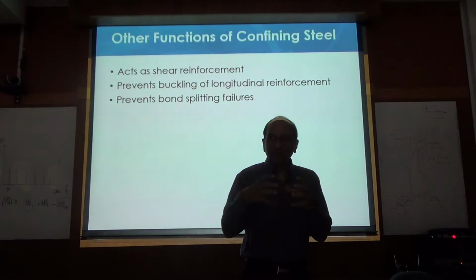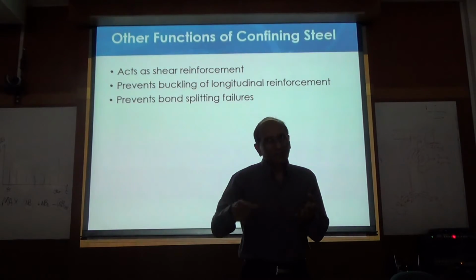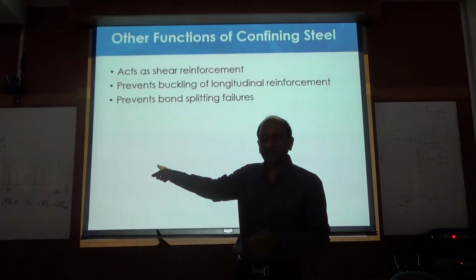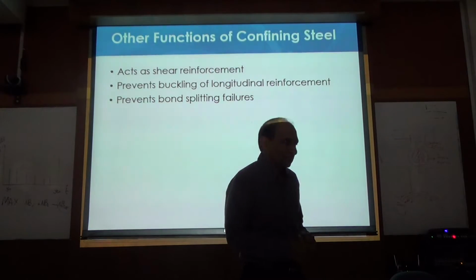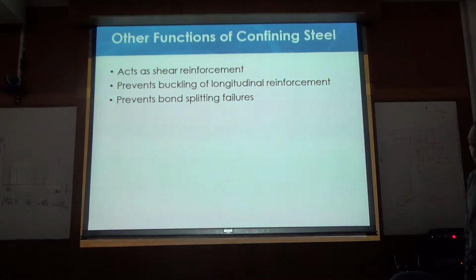So by using confinement or transverse reinforcement, you get a lot of benefits. Confinement and free shear, these three things come free, right? So that's why it is always good to consider the transverse reinforcement carefully.